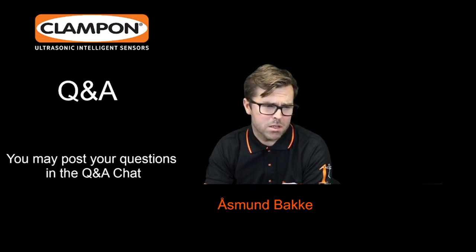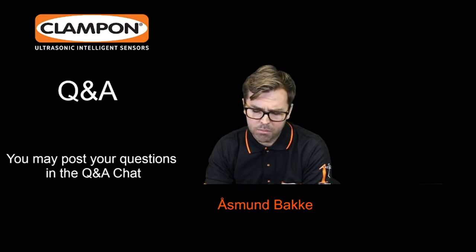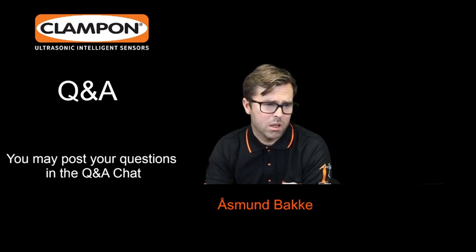The last part of your question regarding ROV: if you have an ROV sailing past a sand detector, normally we pick up sound from that. And that's normal. So that also gives an erratic signal, as you mentioned in your question, almost like we are brushing on the flow line. So we are picking up sound from the ROV.